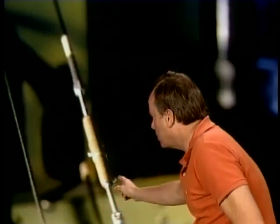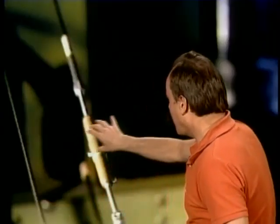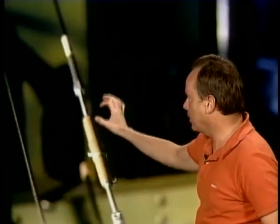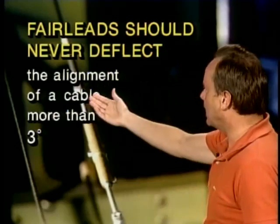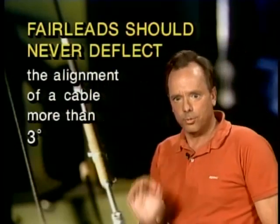All right, now when you're inspecting a control cable turnbuckle for proper installation, you determine that the safety wire ends are wrapped a minimum of 4 times around the terminal and shanks. So make sure that the safety wire is wrapped around 4 times. And that's something you need to know. Now sometimes cables should go through a little hole in the aircraft out to the control surface of the aircraft, and the hole in the aircraft is called a fairlead. The FAA wants you to know that a fairlead should never deflect the alignment of a cable more than 3 degrees.